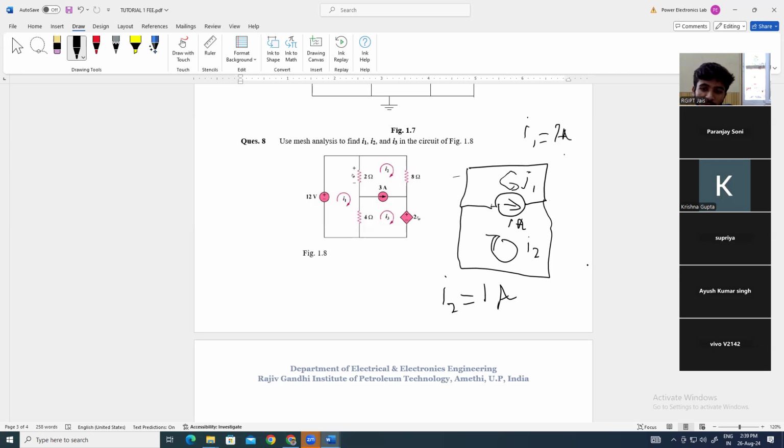But the problem with this node right here would be that this node is receiving 1 ampere current, but the current leaving this node is also 1 ampere and 1 ampere. So this is basically something which does not obey the law of conservation of charge, right? Do you all agree with that? This is basically impossible. We cannot just directly apply KVL and just write 1 ampere and just move on. That's basically impossible, right? Yes, sir.